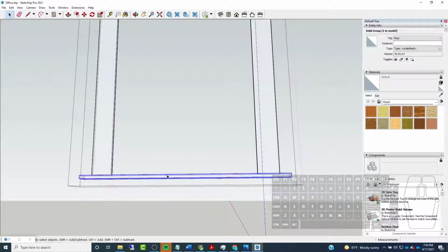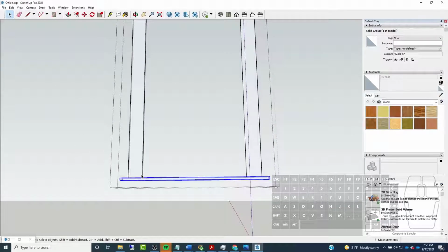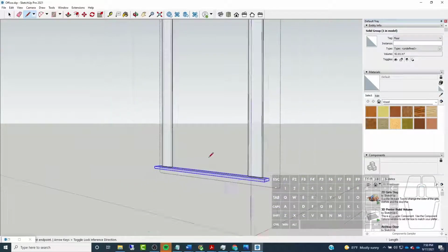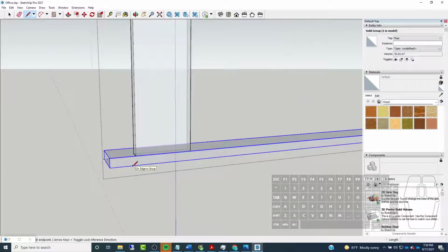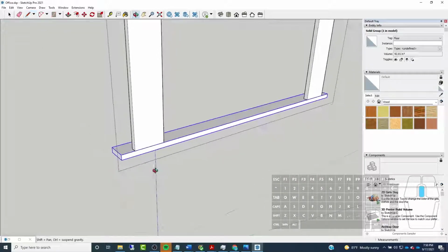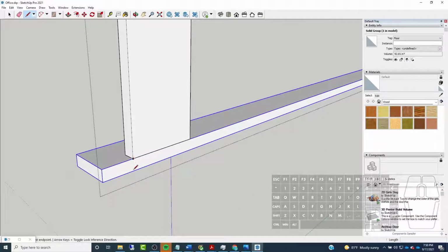And then I got to put my apron piece, which is the piece of casing that runs along the bottom. So for this, I'm going to rotate around to the back side here. And I'm just going to, again, turn off my X-ray. So I'm going to reference this line and then just by hovering my cursor over it, drag straight down to get a spot directly below that. And then I'm going to click and then draw down 4.5 inches.